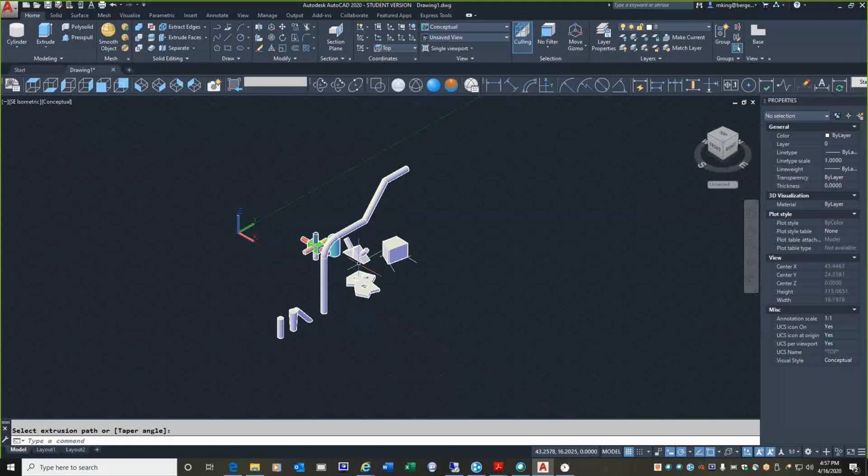Okay, so the next topic on the topic sheet after extrude is polyline, edit, join. Although that in itself is not 3D, we would incorporate that when drawing in 3D, and we already just did. We needed a polyline to create that path. If I had drawn that in regular lines, it would only extrude along the first line segment. Then I'd have to extrude again for the curve, and again and again, and you wouldn't have these nice mitered corners or mitered intersections. So polylines are a big part of the extrude process.